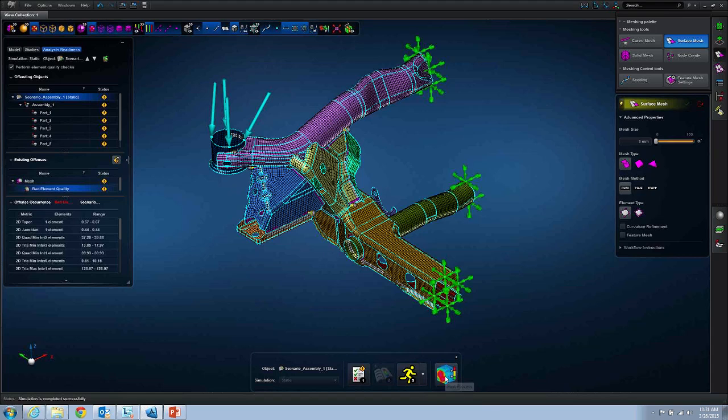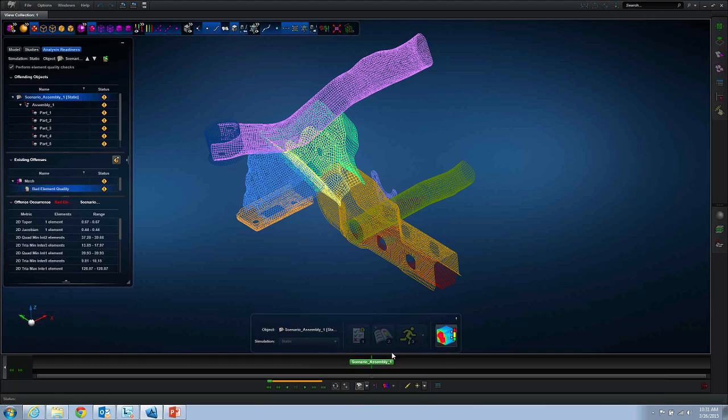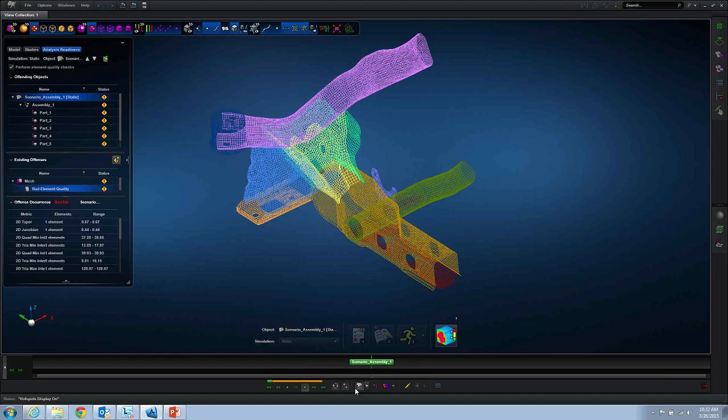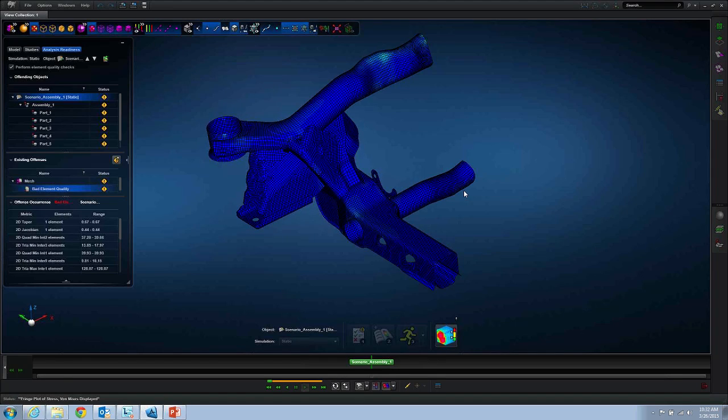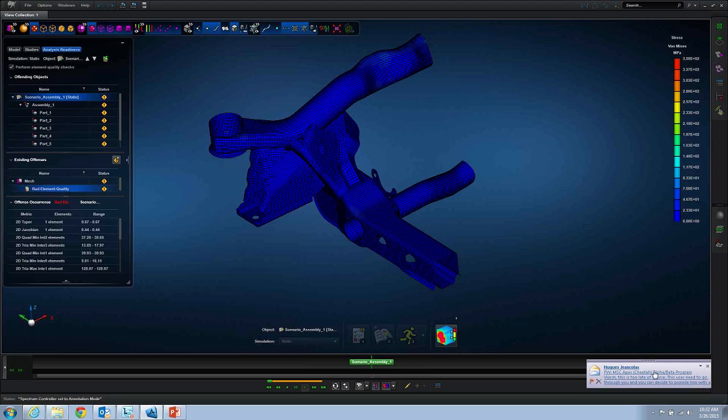And now I can click on post-processor and take you back to the post-processor mode, and now I can take a look at the same hotspots. Before it was about 1.6 millimeter, as you can see now it becomes 1.3. And just to let you know how the system updates and reruns and shows you the behavior, right? And this is the design changes and the static analysis that we did.